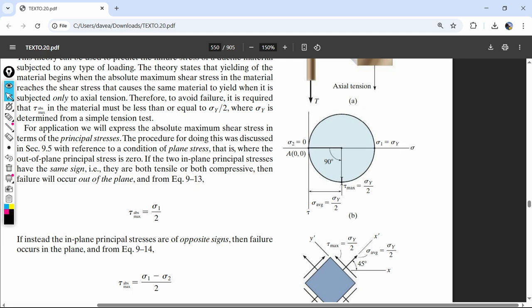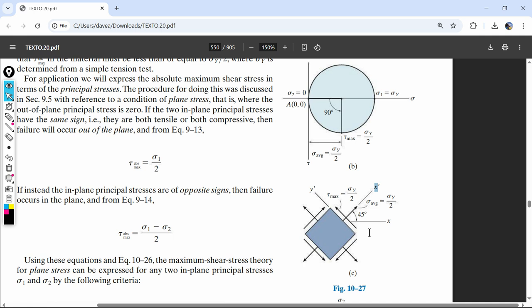If I want to get to the positive shear, it's going to be this value right there. That's the negative shear. It's the same value, just negative. But to get there on the Mohr circle, we use the right-hand rule for angles. It doesn't matter where I start on the circle, but a positive angle is going this way. If I'm at principal stress number 1 and I want to get to the positive shear stress, I have to go negative 90 on the Mohr circle, but this is always 2 times the angle. So in reality, I just have to rotate my element 45 degrees, and we rotate it negative.